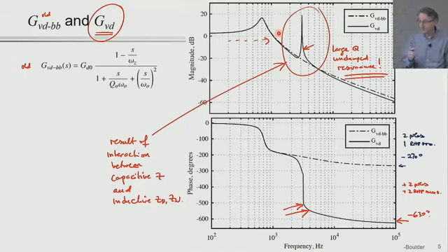So practically speaking, this approach of just trying to shift this up to higher frequency is good, but it has limits. And so normally you can only do it so much. You can do both, right? You can say, I'm going to reduce that capacitance value to something that I can find practically and have still reasonable ripple across it, and then damp it. And that's perfectly fine. So the combination of the two approaches is quite appropriate as well.